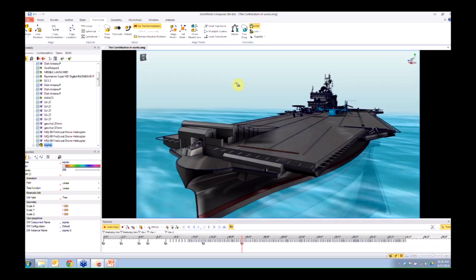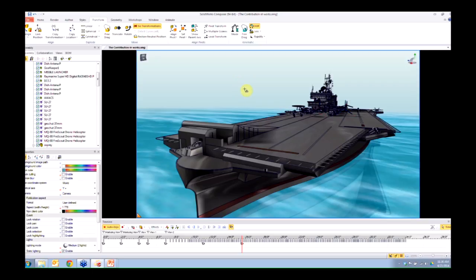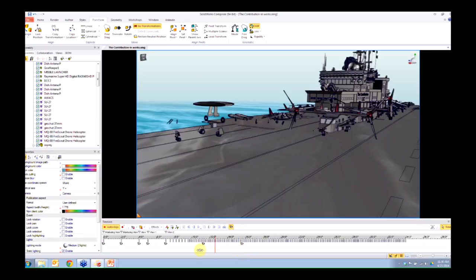That's another little trick. I don't know if anybody has realized that, but if you have assembly selection mode or even part selection mode and you double click a smaller part in a larger assembly, it will drastically change the perspective of the camera angle. And in animation that makes things pretty cool looking, such as this, where we can really get that drastic angle going on. Let's create another camera key. Okay, so now we have that.